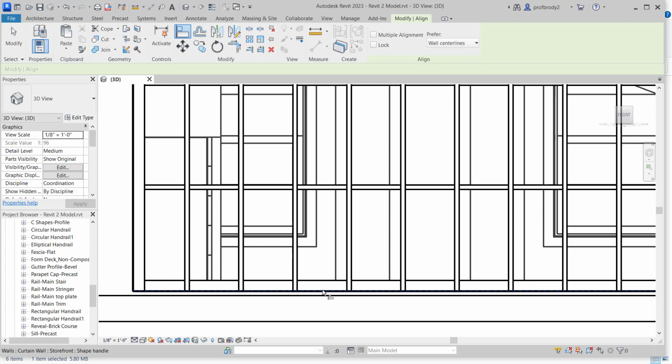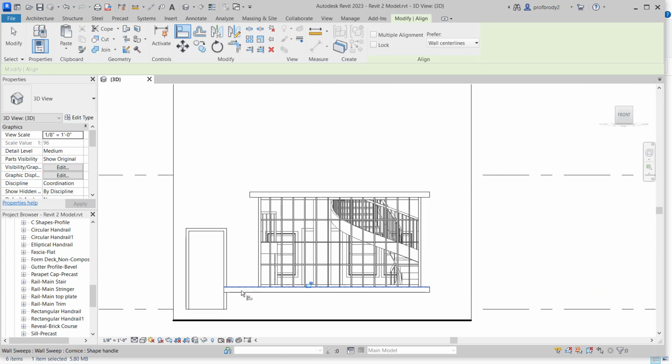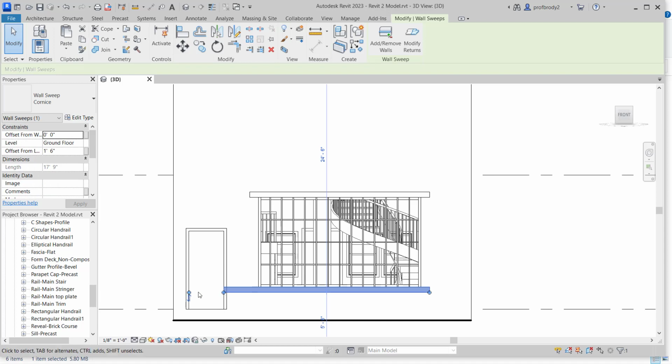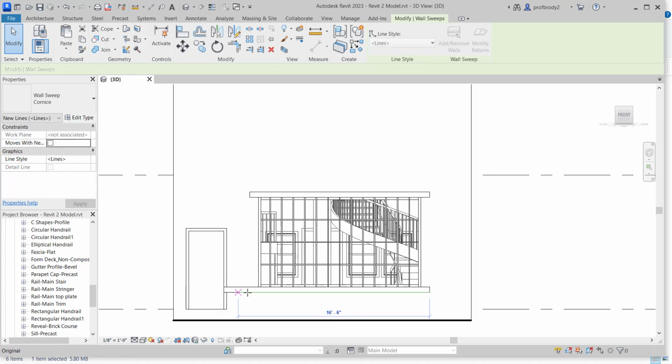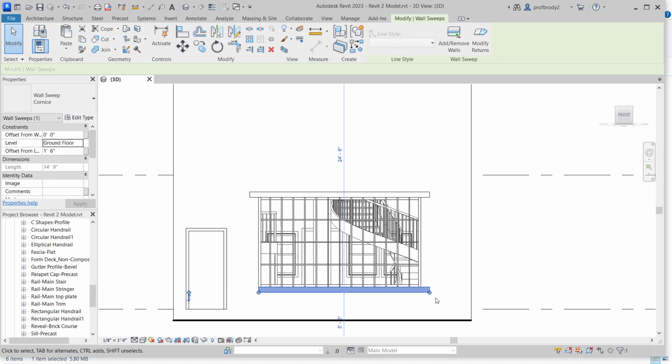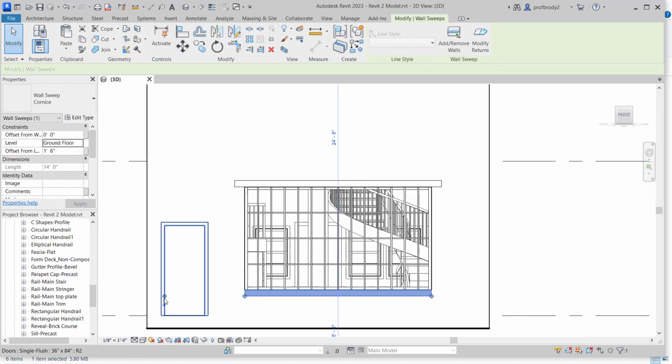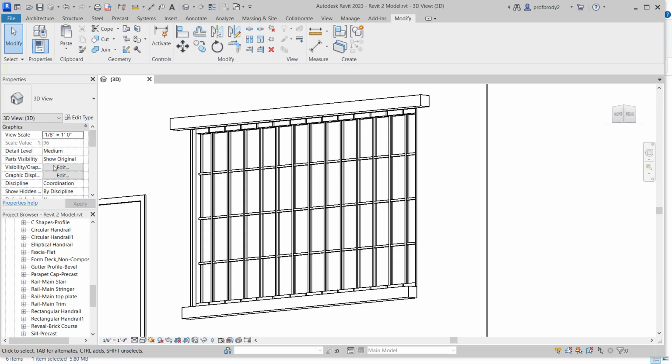Let me just drag it down into position, or like we've done before, use the Align tool. And the trick here is, when you use the copy tool, sometimes you end up with these little scruffy bits, more often than not around doors and things. So the sweeps will connect to the other elements in your project and make reference to walls, doors, and windows. Of course, these are hideous looking. We don't really want to use these as our lintel and sill.